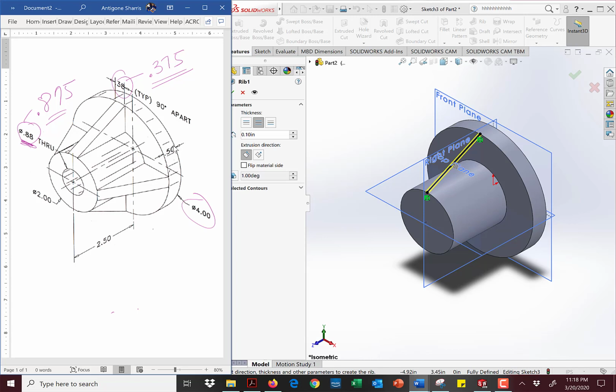Generally speaking, the drawings that you get to see online and might model come out of probably real parts. I don't know where this one came from, but it was in a book. I forgot from when, but it was passed down to me, so now I have this model. It does show things to 2 decimal places, but that doesn't mean the numeric value you see is really to 2 decimal places. So please always be cautious about just typing in the number you see, because it probably isn't the real value.